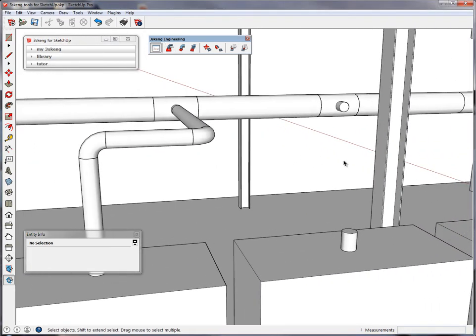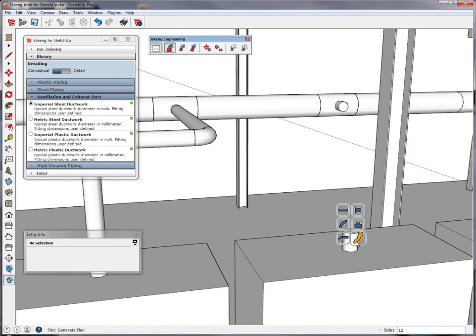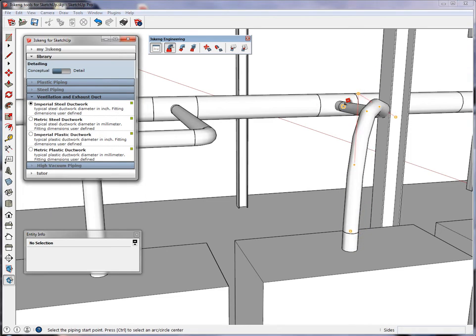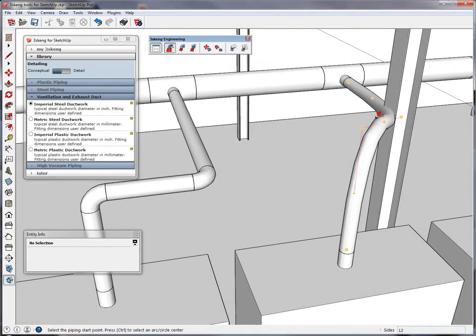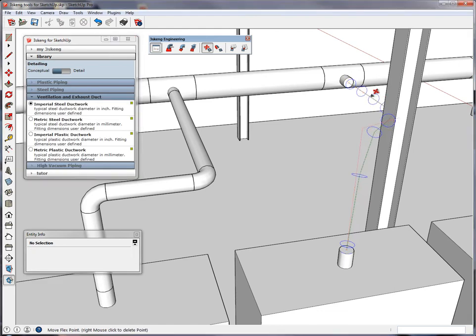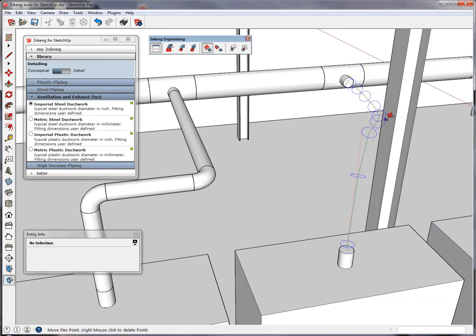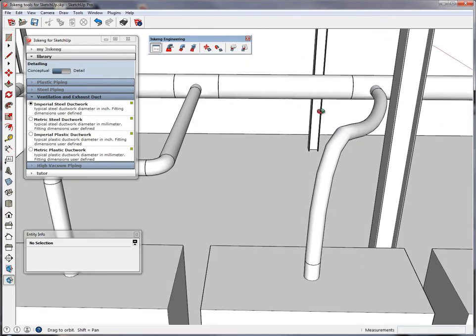In exhaust, you sometimes have the requirement to do flexible connections. We can also do this. We just add a flex. Now we can see that we have a collision of this flex with our steel. In this case, we just hit the edit, hover over our flex, make a left click, and give it another bending point. Now we have the possibility to lock the axis and move our flex away from the steel beam, and we have a good connection now.